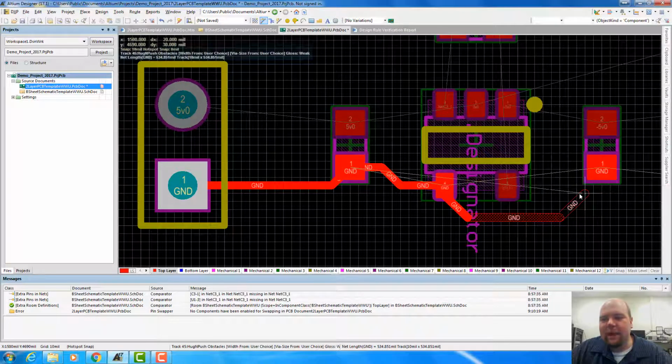Now the nice thing about this is when we do it like that, the software can help us with some things. Like for instance here, the software can automatically calculate what that 45-degree angle has to be to meet us at the pad. Let's say we hadn't done that. What if we just clicked it here? Well, now we're going to have some weird connection to get there, right?